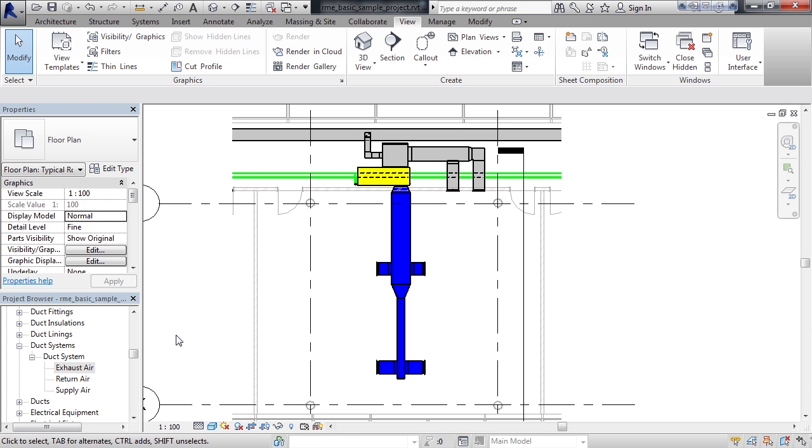For example, the system on our screen right now is a duct system, HVAC system, if you will, for supplying air, hot and cold to your building. Let's say you wanted to run inspection against that. Well, there are analytical tools to let you look at flow rates, pressure loss values for this given system. Specifically for systems, the tool is called a System Inspector tool, and we can launch that tool from the system